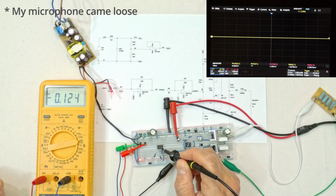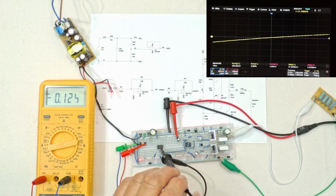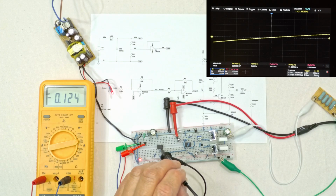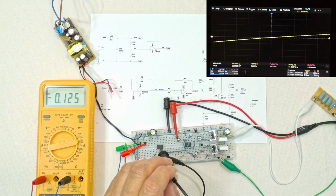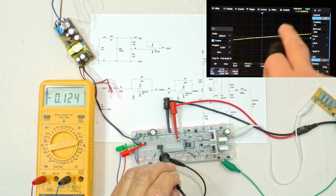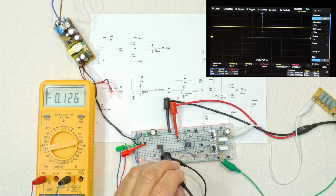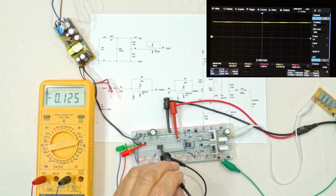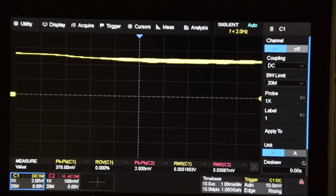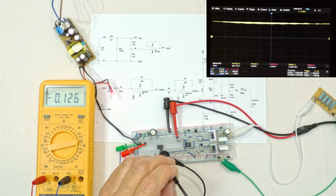Let's take a look at the reference voltage. This is not good. This should be a level, stable 6 volt DC, and it's clearly not. Let's turn over to DC. Well, this should be a stable 6 volt. As you can see, it's clearly not. So I would say the issue is with this reference voltage.